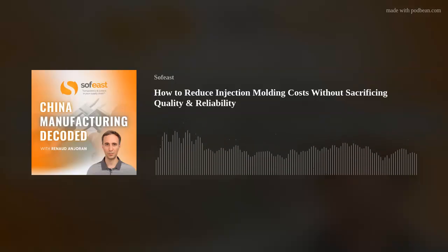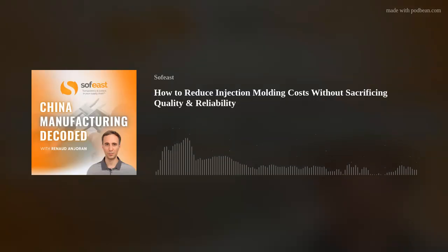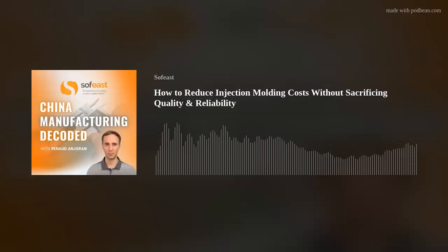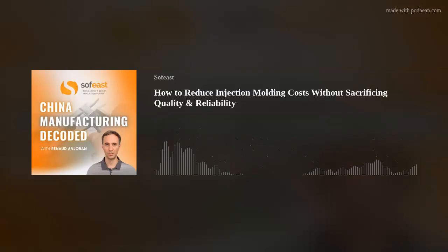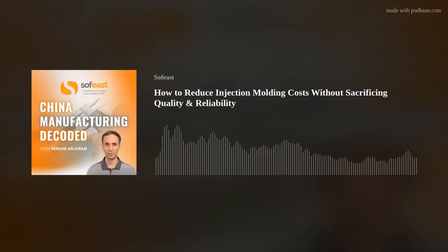Another one that is overkill, which a lot of people, and I'm going to come onto this again a little bit later from a vanity point of view, is the cosmetic or the surface finish. Okay. Now, if you've got, for example, a consumer electronics part, inside the outer case, you've got a battery, and that battery is inside a cover, okay, in a separate compartment. If you're specifying you want a surface finish on that cover, on the lid for the battery case, why? No one's going to ever see it.